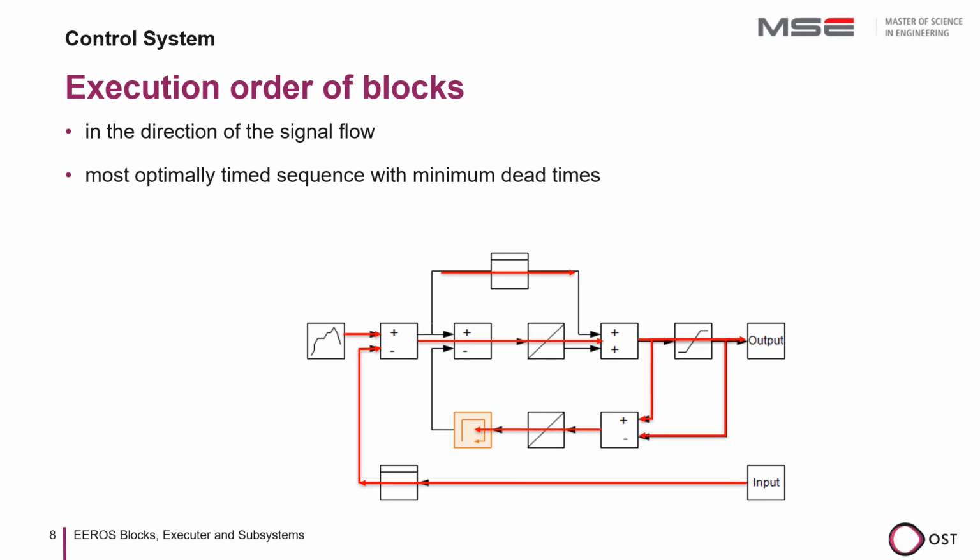Above all, it must be ensured that all signals presented at the input of a block have been updated before the block is calculated. Closed loops must be split at one point. The value of the signal is stored and passed on with the next call on the time domain delayed by one cycle. If necessary, the timestamp must be adjusted at this point.